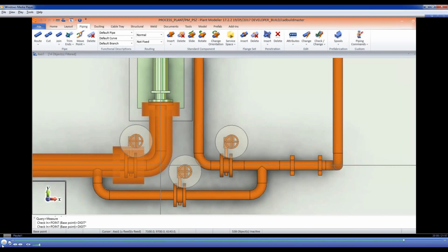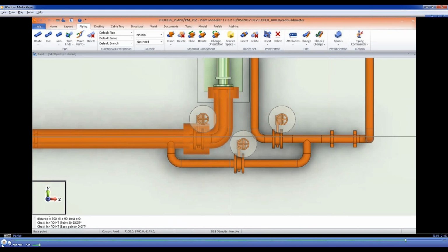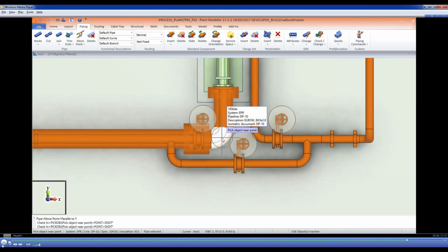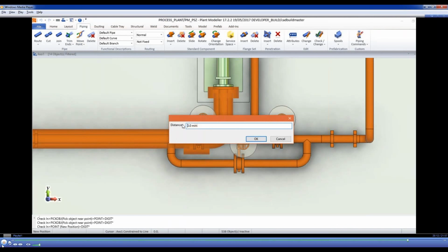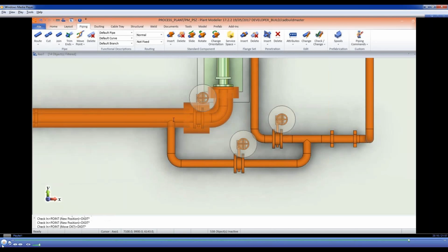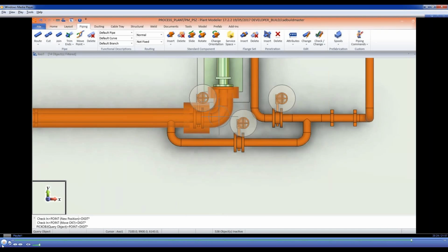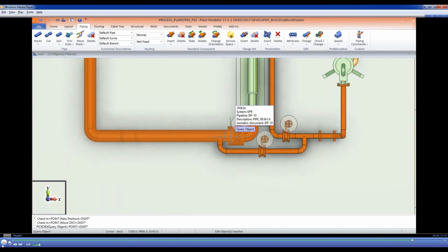Then I could move this pipe a little bit closer. Now it is 500 millimeter, but I can make this place tighter by moving this whole set of objects 200 millimeter closer to the pump. And same thing to the pressure side, just picking this corner and moving it to the same location as this other corner. And everything will follow.